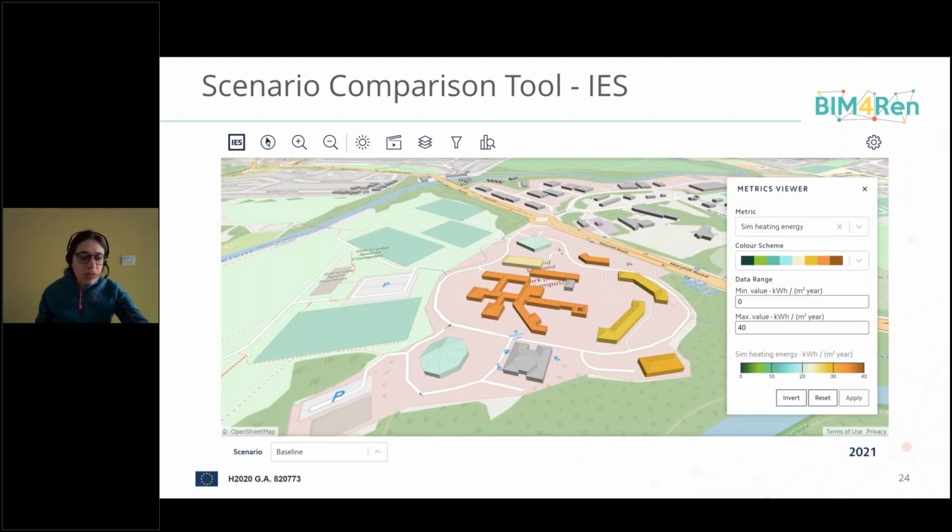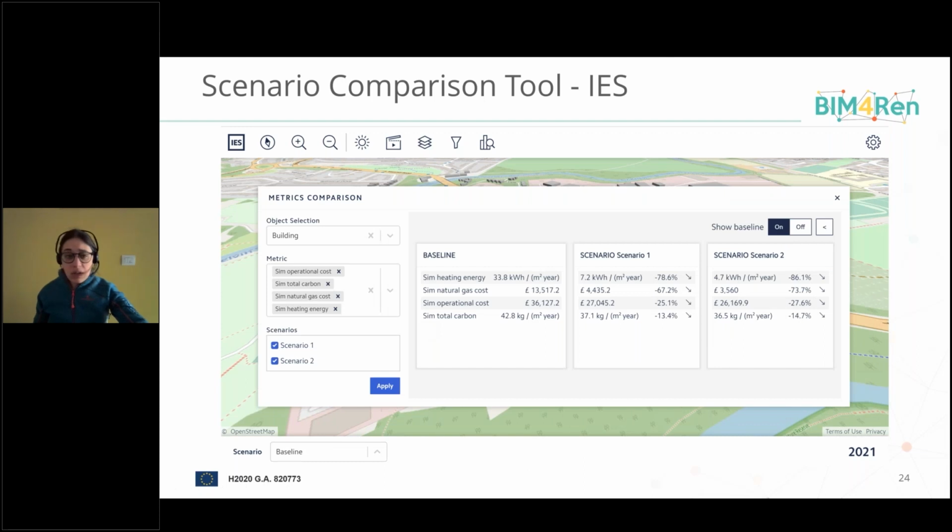The tool already uses actual buildings in their context. It uses geometries that can be imported from OpenStreetMap, for example, and the user can add the basic configuration, create a baseline, add renovation interventions, and run cloud simulations for the building. Then the results can be compared. You can see this example in more detail in the YouTube video. In scenario 1, the intervention we were testing was a replacement of the boiler with a heat pump, and scenario 2 also added passive interventions.